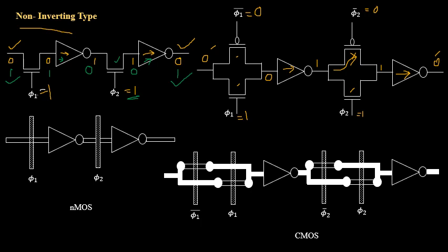Let me explain considering the other case, that is logical 1 state. Phi 1 is 1 itself. So now it will take this particular path because it has to pass pure logical 1 state. So this is logical 1 state obtained. 1 is passed through an inverter, so it will give the output as 0. I will assume this is equal to 1 and this is equal to 0, because if phi 2 is 1, then phi 2 complement should be 0.